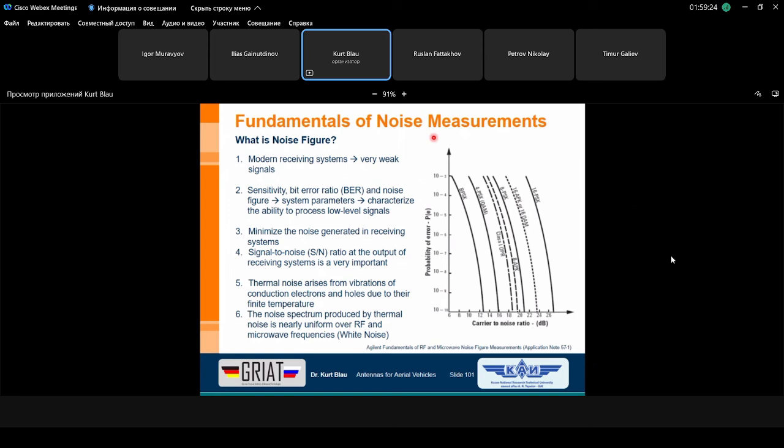And in case of a vacuum tube, you have to apply an anode voltage, and then you have an anode current going to the cathode, the cathode current. It depends on the number of grids. At least you also have a current flow through a vacuum tube, and all these currents produce noise. And again, plus the noise coming from the outside, from thermal things, from the temperature of the environment.